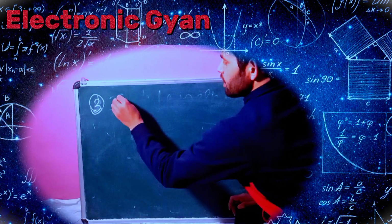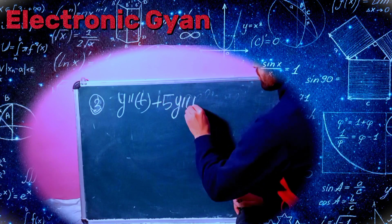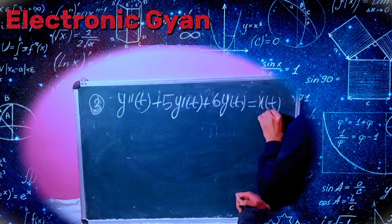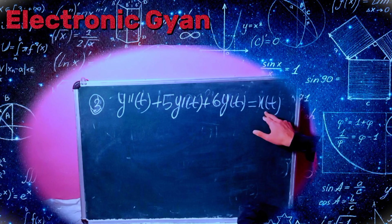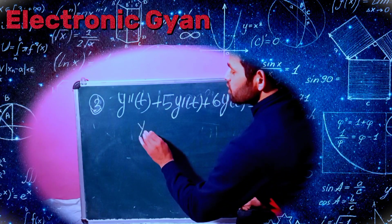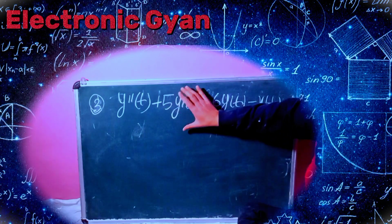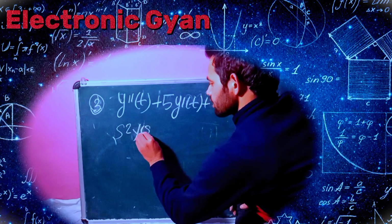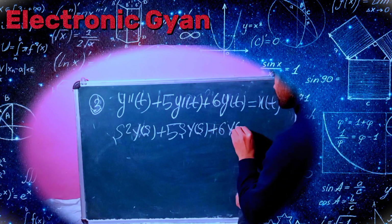For the impulse response of the system, the given differential equation is y''(t) + 5y'(t) + 6y(t) = x(t). For the impulse response, my input is an impulse and the initial condition is 0. Now by applying the Laplace transform on both sides, what will we get here? We get s² Y(s) + 5s Y(s) + 6 Y(s) is equal to what?